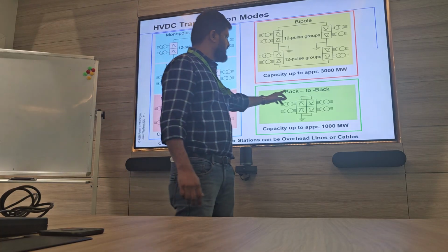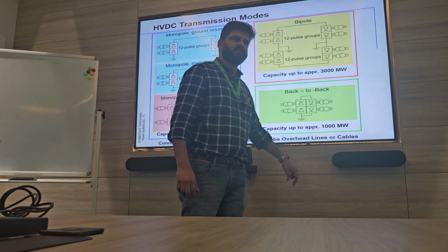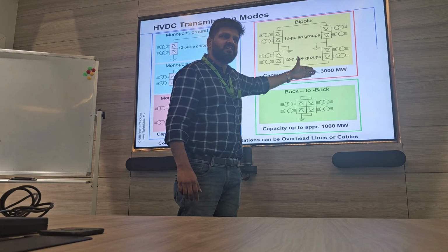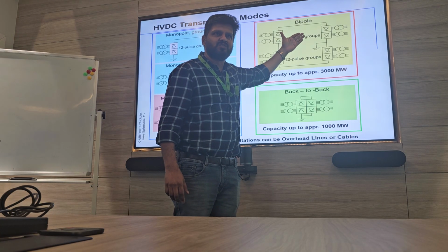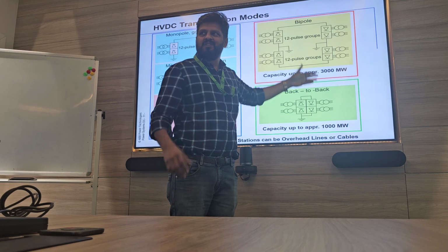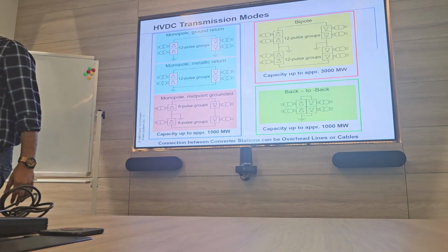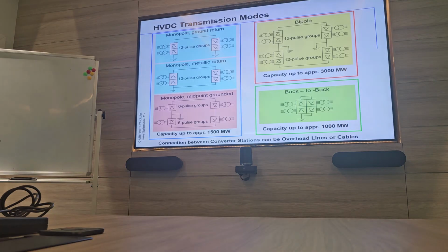Normally this is very small, 1000 megawatt only. If you want more power, you need to transfer by transmission line. Now China is transferring 9,000 megawatt, 10,000 megawatt, at 1,100 kV. For example, for any of these projects, if we are going to move 1,000 megawatt instead of 3,000, we shall go with AC.